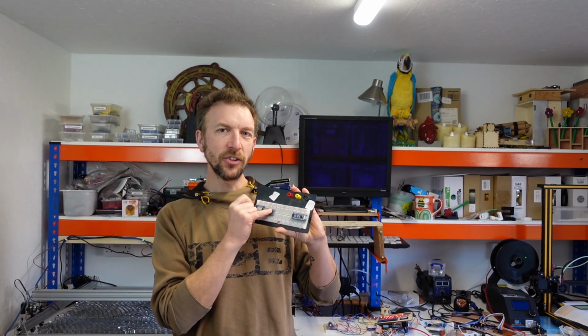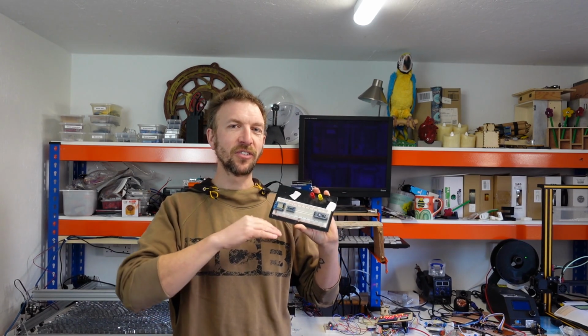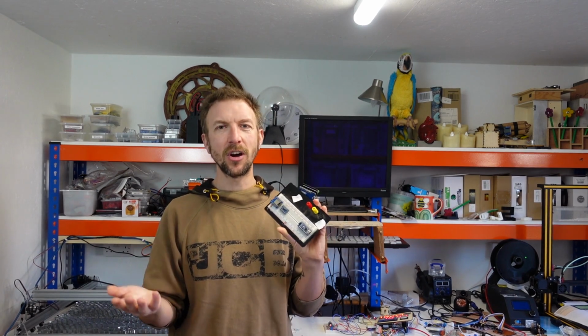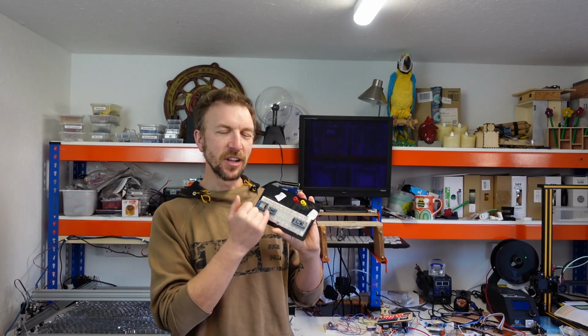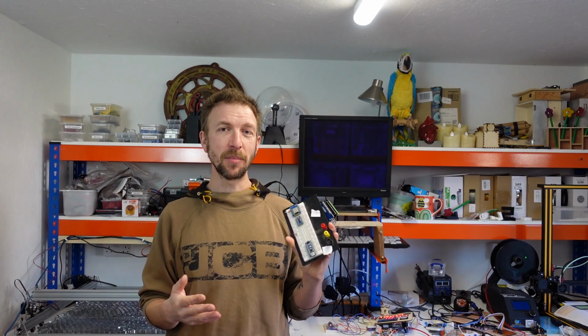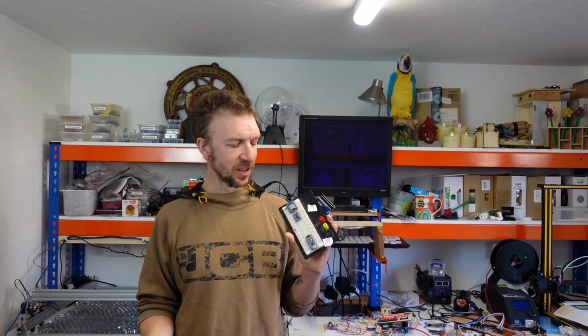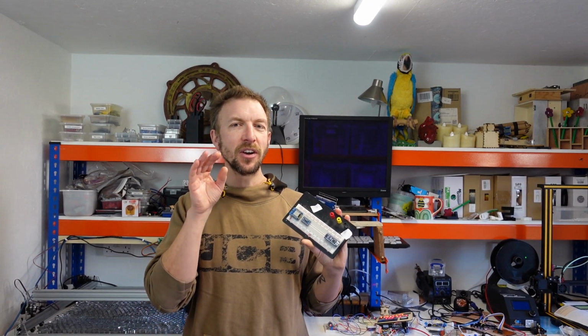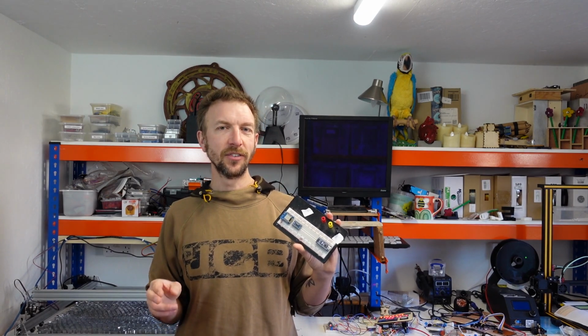And when you've gone through a logic level converter, my guess is that it's introducing a delay or distorting that timing pattern slightly between the low signal and the high signal, and as a result the data is getting corrupted and it doesn't work. So that doesn't work either. Then I thought, okay, well, I could use a 2-wire data signal instead.